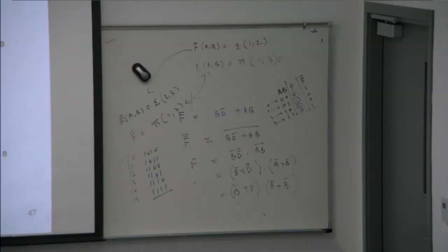Now if you look at the Karnaugh map, we have 16 possible combinations. What are the 16 possible combinations? 0, 1, 2, 3, 4, 5, 6, 7, 8, 9. What are the invalid combinations? 10, 11, 12, 13, 14, and 15. So all of these are X; this one is 1111. It belongs to what? 15. Got it? Any questions? Should we proceed?